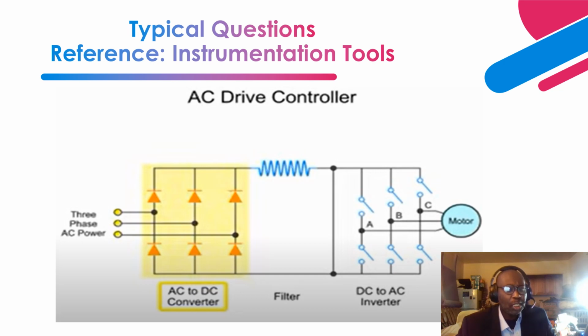Okay, so this is the input voltage, right? You sketch it, 415, 430 volts, right? Then how do you achieve that 430 volts or 450 volts that is required by the variable speed drive? There is a step-down transformer, right?